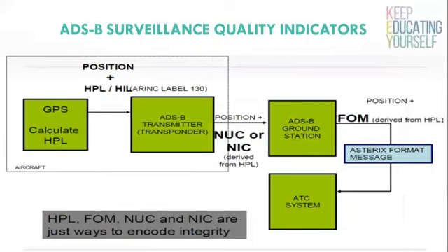Thus, the aircraft will obtain its position from GPS. Thus, GPS integrity comes into the picture. RAIM, Receiver Autonomous Integrity Monitoring, is a technology developed to assess the integrity of GPS signals in a GPS receiver system. It is of special importance in safety-critical GPS applications such as aviation or marine navigation. GPS does not include any integral information about the integrity of its signal. RAIM is considered available if 24 GPS satellites or more are operative.